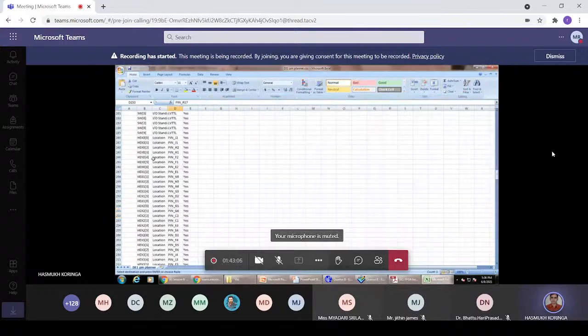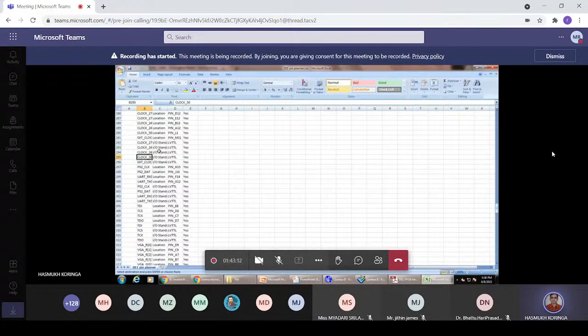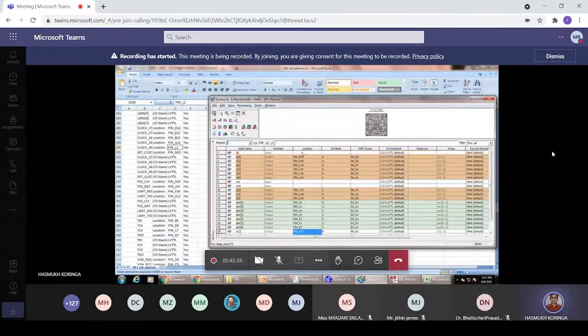For the clock we use the internal 50 megahertz clock, right, because we'll give this to the clock divider. After the clock divider, we'll get a 1 hertz clock. The pin number of the 50 megahertz clock coming from the crystal is connected to the L1 pin. So let me use this for the clock, as this internal clock, so there is no need to give it manually through the switch.